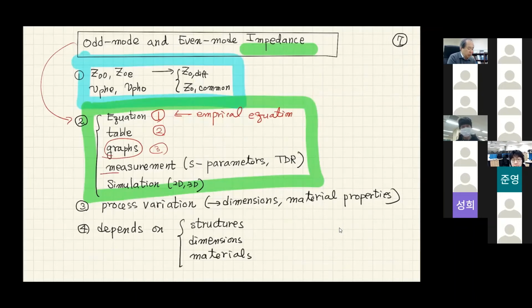Also, you can do a measurement of your PCB. In most PCB companies, they regularly check their PCBs to measure the impedance. Their customers are asking them to maintain a certain single line impedance and differential line impedance. And of course, a PCB process has certain variations, so they want to maintain the quality of their impedance, and this is how they verify that.